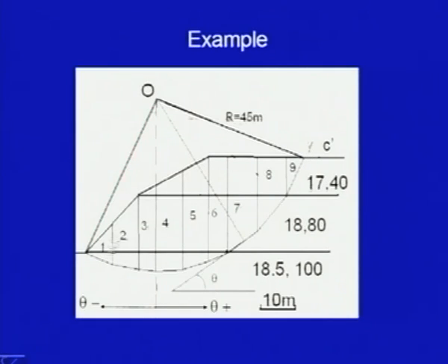It was not a homogeneous slope, and we have already taken up this problem, and I had discussed how you should take the slices. You can take equal width also, there is no problem in that, but wherever this profile is changing, I have preferred to take the slices there. So, the computations become a little bit easier. So, here this was a slope, then we have drawn this circle, and then I have joined these 2 points by straight lines,